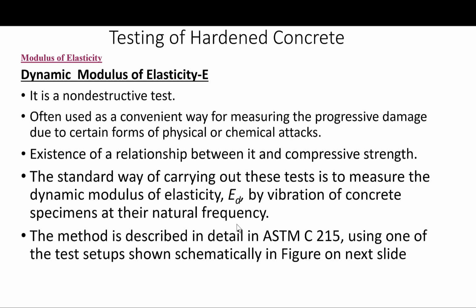So we can progressively measure the modulus of elasticity over time to see how the concrete is being affected or damaged. For this purpose, dynamic modulus of elasticity measurements are very convenient, since they are non-destructive and since there is also a general, although empirical, relationship between the modulus of elasticity and the compressive strength. So it serves many purposes.